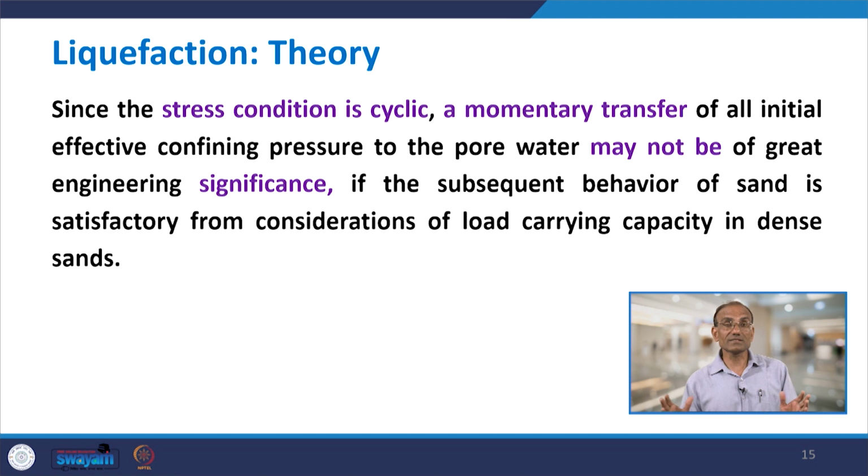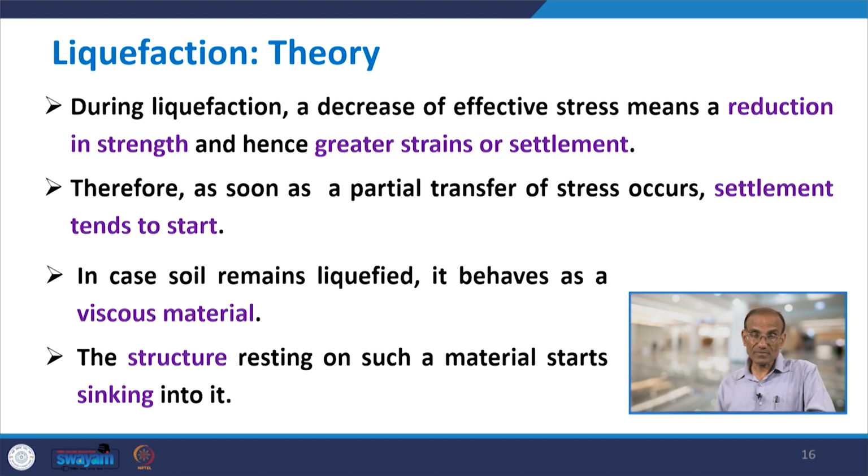So, it is not necessary that whenever liquefaction occurs there will always be damage, because this liquefaction phenomenon could be momentary, where the load is transferred to the pore pressure only for a fraction of a second, and then in the next cycle reversal takes place, and the behavior is satisfactory.